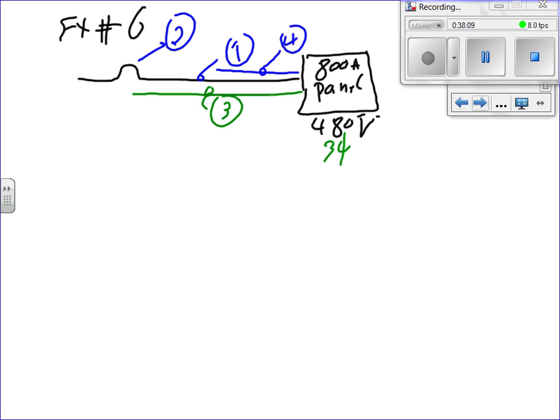When we came up with the 800 amp, we took into consideration the continuous, we added the non-continuous load with the continuous load, and we kept adding them until we landed at an 800 amp panel. Okay, everything taken into consideration. It's a panel, we size it. You guys, I'm going to be walking you through how to size it.